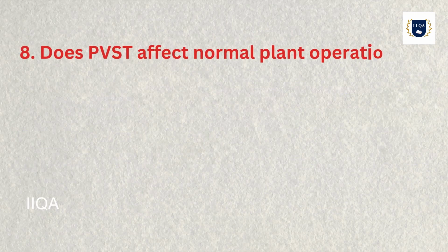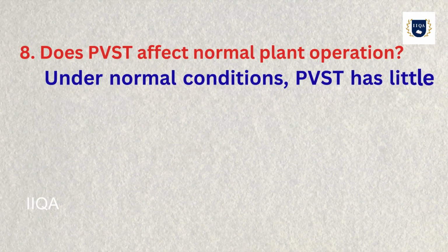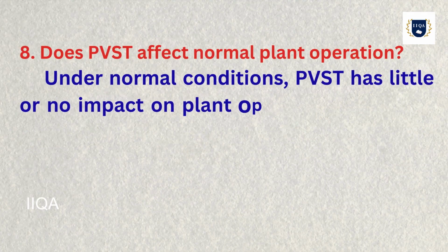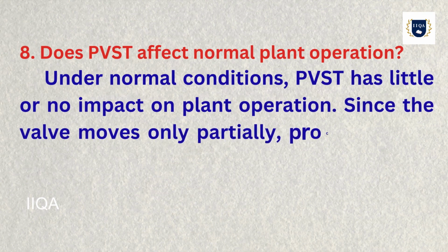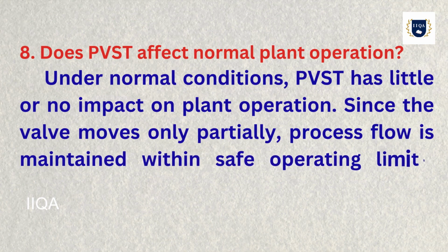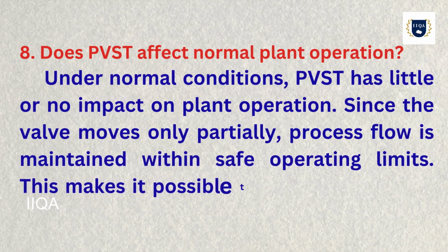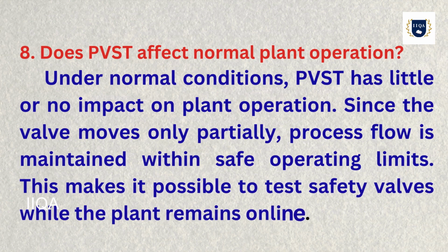8. Does PVST affect normal plant operation? Under normal conditions, PVST has little or no impact on plant operation. Since the valve moves only partially, process flow is maintained within safe operating limits. This makes it possible to test safety valves while the plant remains online.